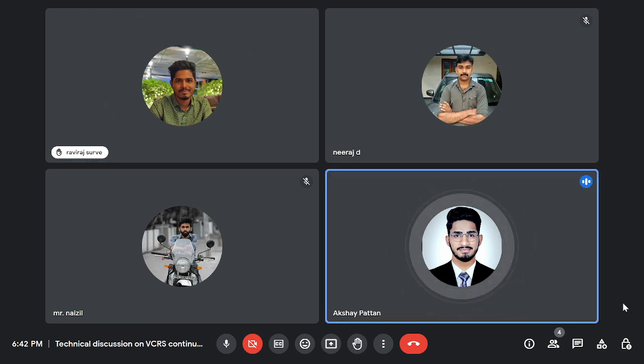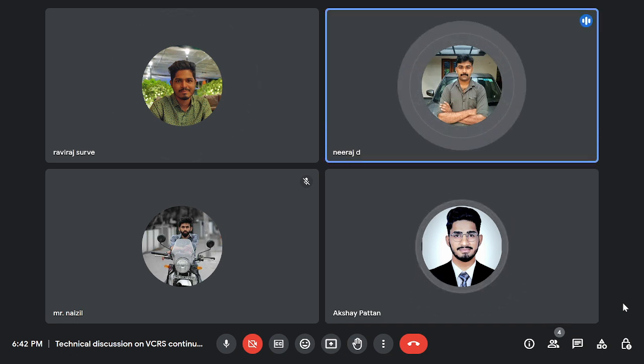So this answer is partially right, because the term circuit which you are mentioning is not actually correct. There are actually two evaporator coils. Basically, the cooling effect is taking place in the evaporator coil, right? The freezing or cooling effect is taking place at the evaporator coil only. So there are two different evaporator coils, one for the freezing compartment and one for the vegetable compartment.